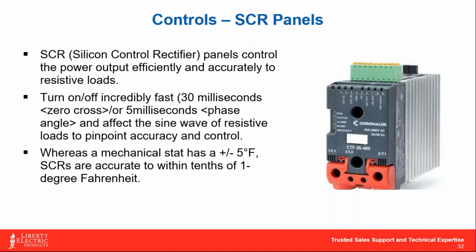And I think that another characteristic or advantage of an SCR controller is that when you reduce the amount of voltage or power going to the heater and therefore reduce its output, for instance, if I had a 100 kW immersion heater and I wanted to run it at 20%, now I'm only consuming 20 kW and I'm only paying for 20 kW, not 100 kW, which is a little bit different sometimes from gas.